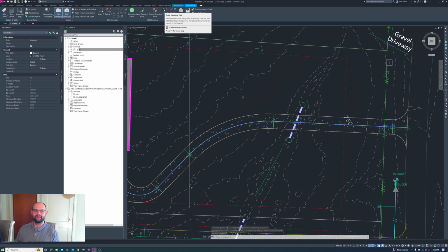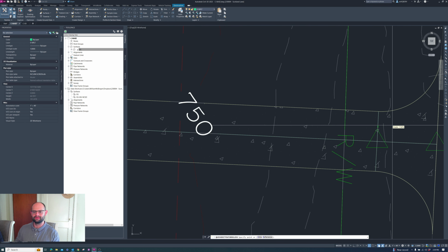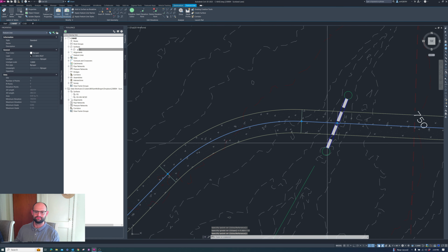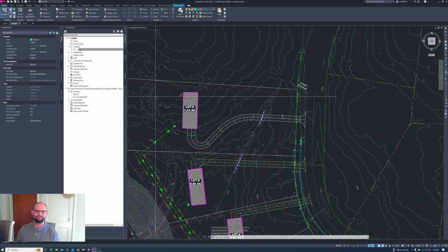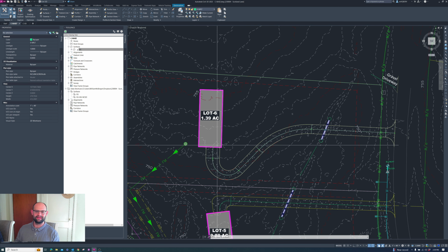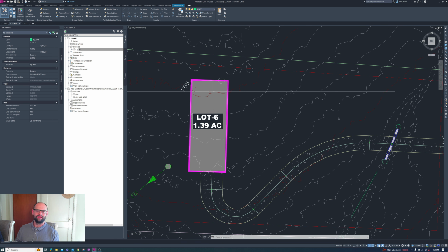Now we're going to use the edit elevation again. And keep up with that theme to generate the normal crown. Down 2% away from the center line. So we're set up to the low point of the road here now. Let's work back towards the pad. We want to get this area kind of mostly cut, maybe a little bit of fill on this corner. This is the higher end of the existing topo, lower end here.